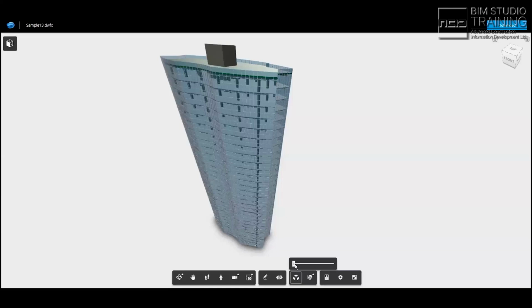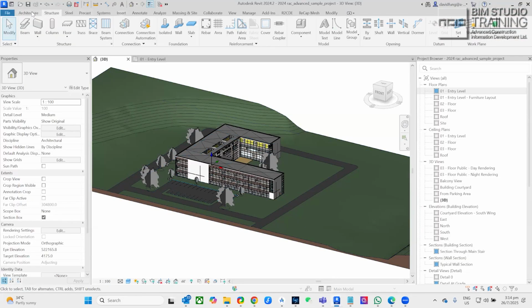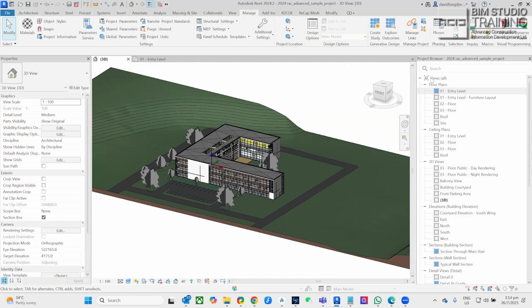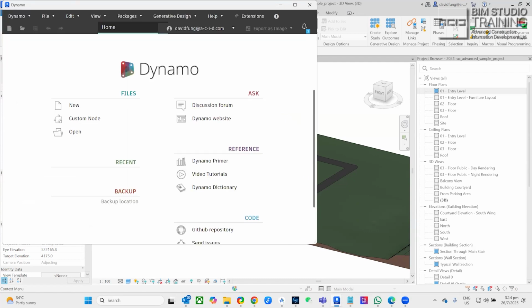All right, so this is automation. We automate the process. Now, if you don't know how to use Revit, these are all the commands that help you to draft things out. Not good enough. If you go to Manage here, that is where I was using Dynamo. Dynamo is an add-on to Revit, and we can let our thinking, our relationships, tell it what relates to what. So we change the parameter and see the consequences. We change the top ratio, and everything will change. These kinds of rules.